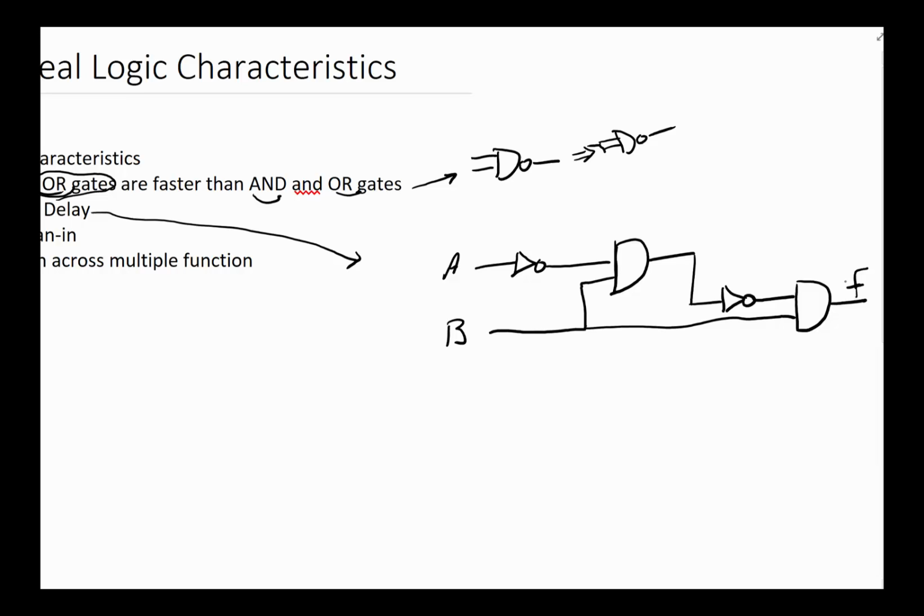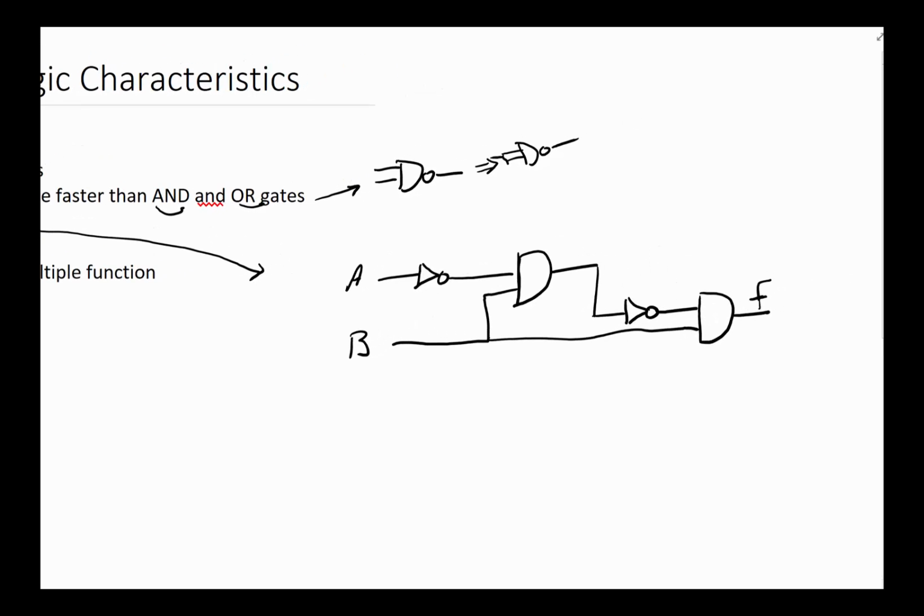So far we've been really worried about logic: can I tell the expression of F with respect to all that? That's great. Now what we're more interested in is how long it takes for this input to make it to the output. A lot of times we can't tell exactly how long it will take; what we are really interested in is the maximum propagation time through this. Sometimes someone might put it in terms of a critical path: what's the critical path through the circuit? What's the maximum propagation delay?